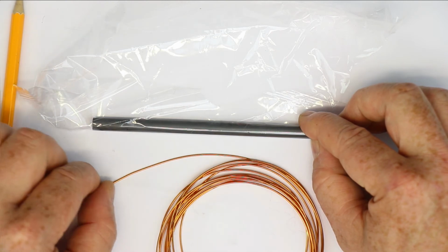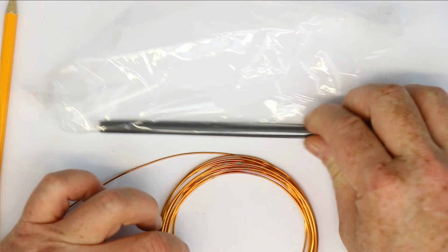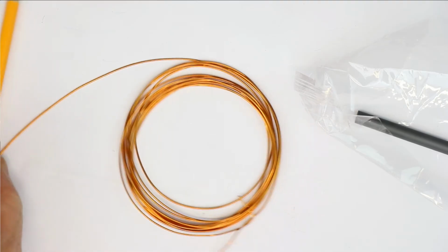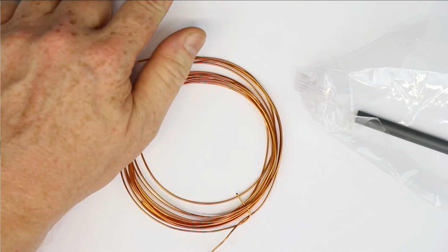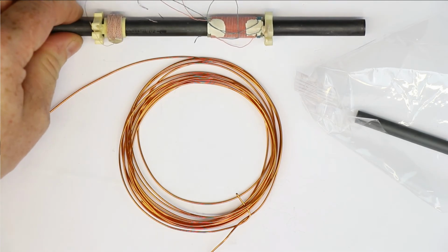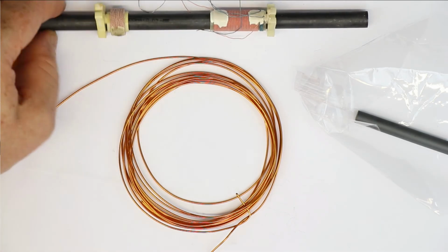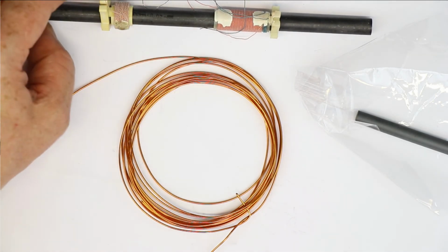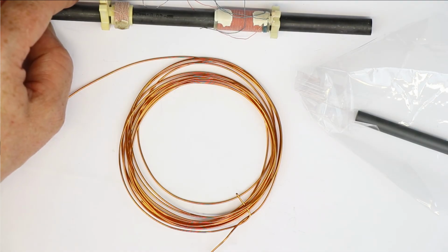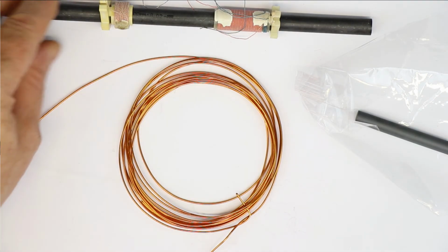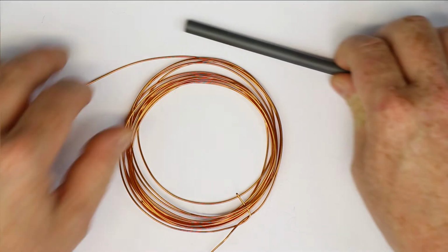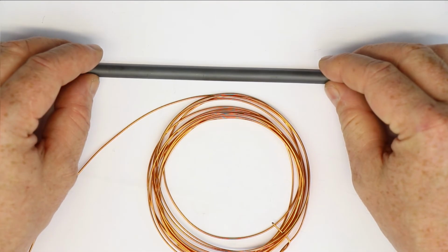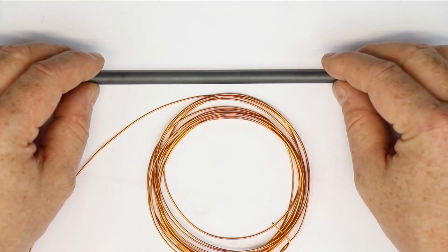And next is, what wire do we use? Well, you can already see it, and I already mentioned it. Never use Litz wire for shortwave reception, for anything above 1 megahertz. In that frequency range, proximity effect and skin effect take over, and there is only one remedy.